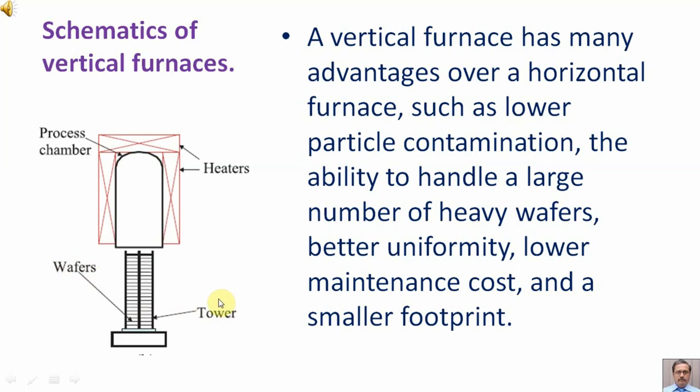A vertical furnace has many advantages over a horizontal furnace, such as lower particle contamination, the ability to handle a large number of heavy wafers, better uniformity, lower maintenance cost, and a smaller footprint.